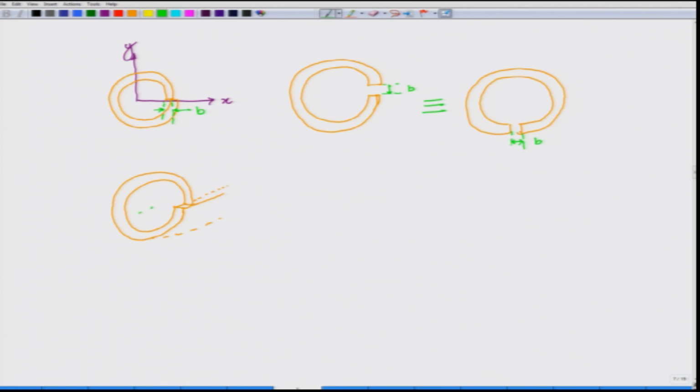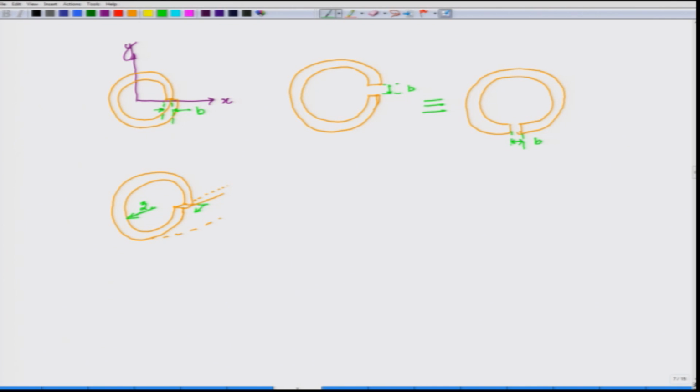This was the z direction, or actually, coming out of the page is the z direction. So, the faces have been translated along the z direction, and again this gap that has been created will be the Burgers vector, from what we already know about dislocations.